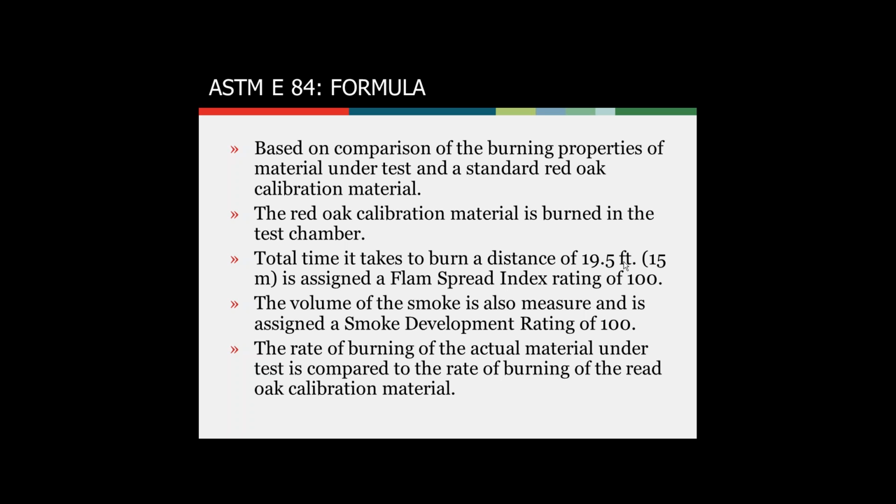In the real world today, you have a zillion products that do not burn as cleanly and as evenly as wood, and the ASTM E84 committee came up with a formula. You plug in the distance burned and how quickly it burns, and that formula gives you a smoke and a flame spread index. But again, it's not that same simple formula that was used when you were comparing treated wood versus untreated wood.